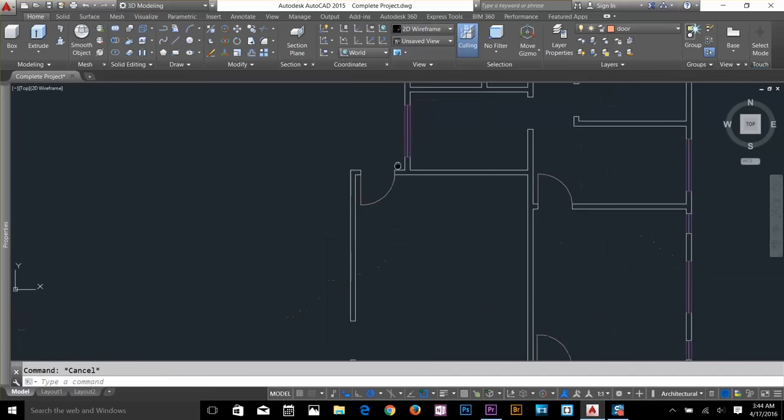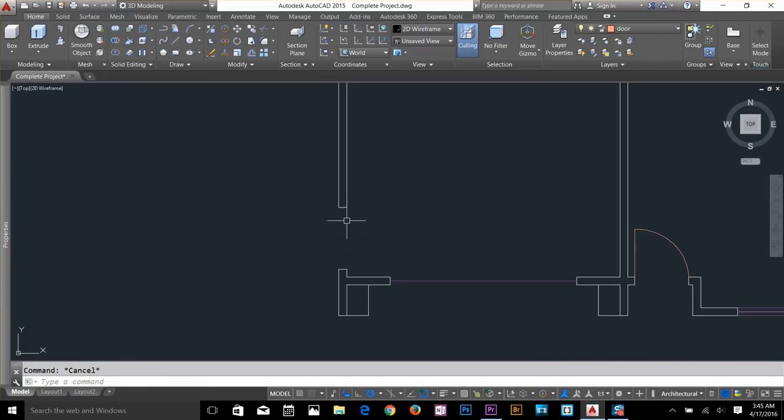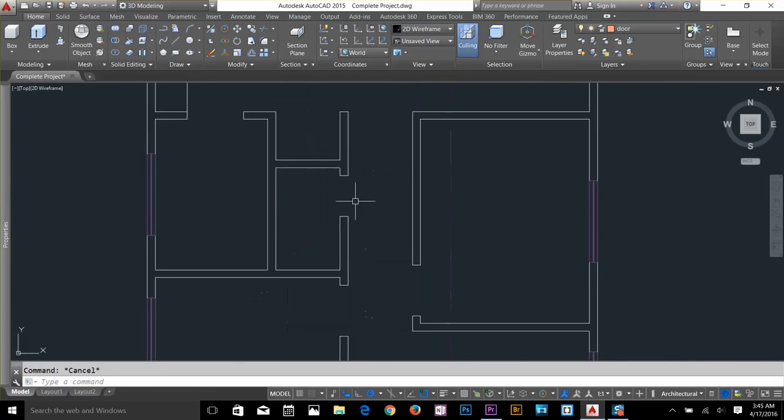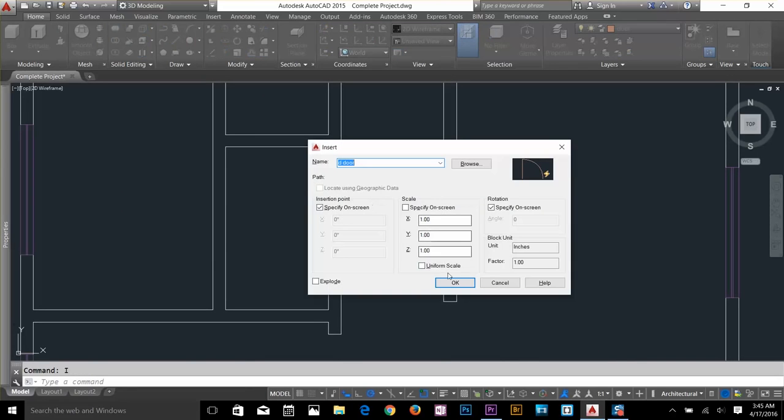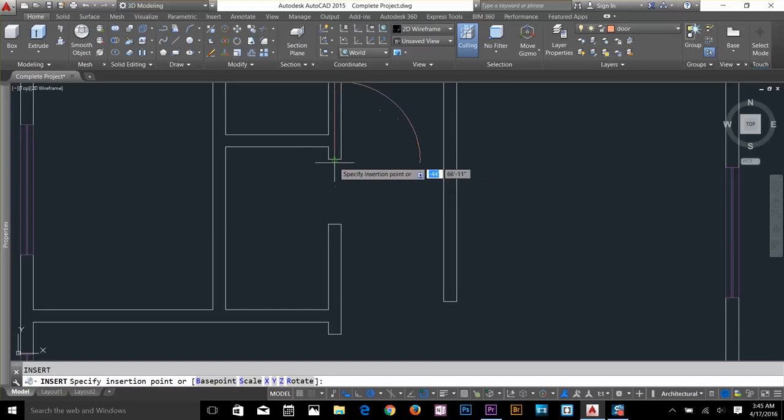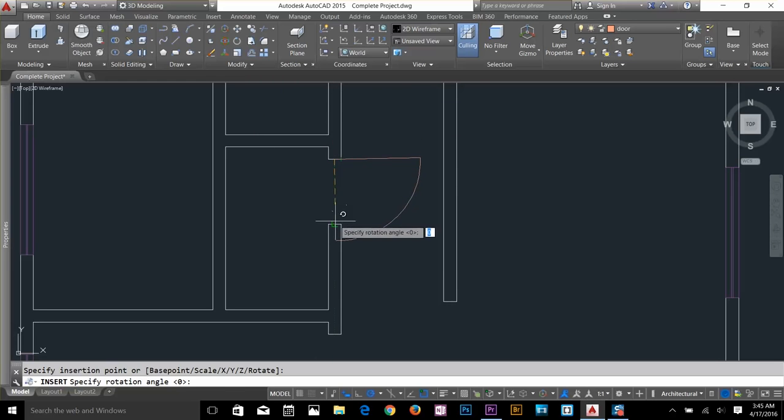And now I've got one of the doors. Let's say it's a smaller door now, so press I, spacebar, OK, and then I'm going to drop the door here. The angle would be, just leave that angle there, maybe here, and click here, and then you need to flip that door.